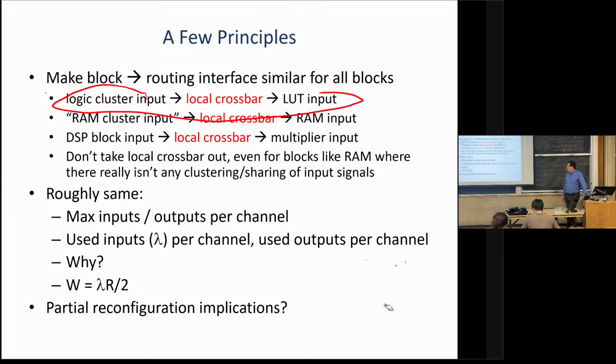There are a few architectures. There's one called the 6200 by Algotronix that was built years ago for partial reconfiguration. It was bigger than other FPGAs, but really easy to partially reconfigure. Xilinx bought them, but they end-of-lifed that architecture. So I guess that doesn't prove that architecting primarily for partial reconfiguration is a bad idea, but it doesn't prove it's a good idea either.